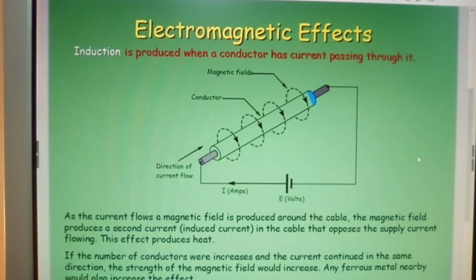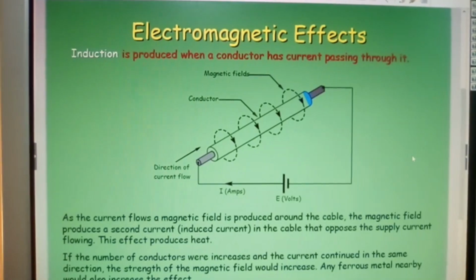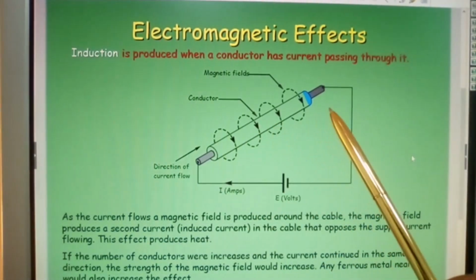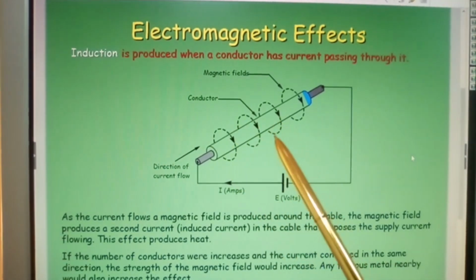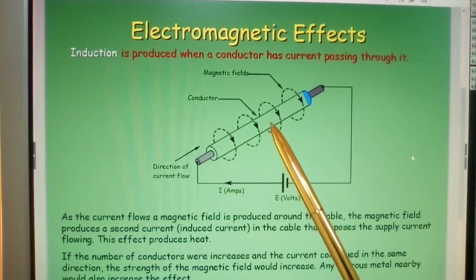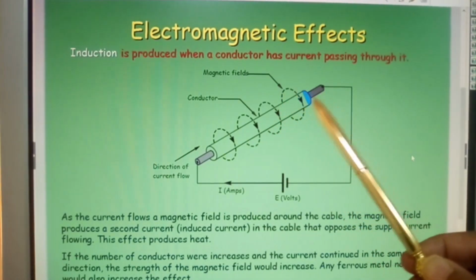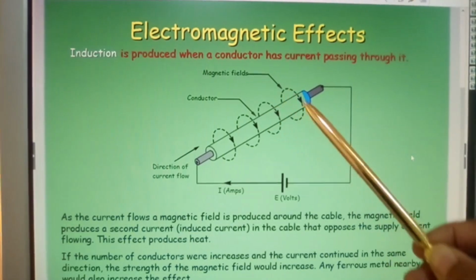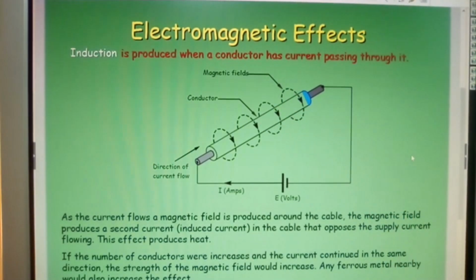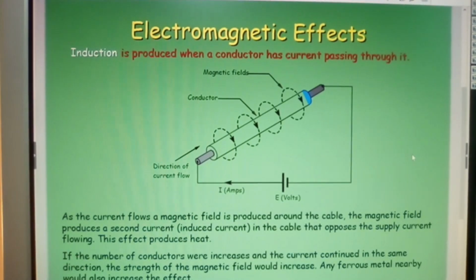Okay. So what you're saying here is that we do not run single conductors in any form at any point in time because it has a magnetic field which will cause an effect on the cable itself. So we'll run a live and neutral. This will allow, if we have two cables here, this will cancel out the effect of one against the other, okay? Thereby reducing the magnetic induction.